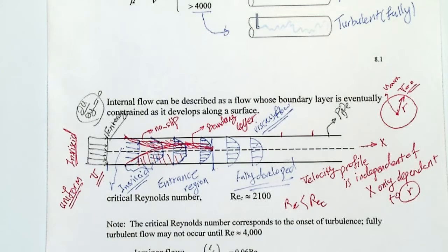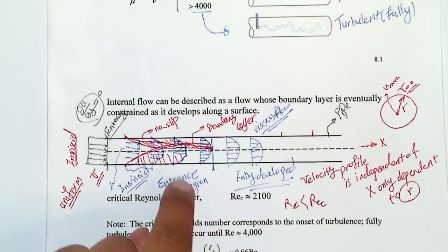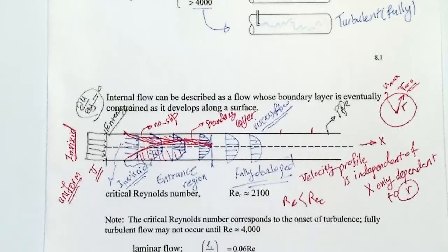So we are talking about laminar flow, which is most of the flows, especially in the human body for vessels, and also in most of the things that you have in food companies for washing. You will see that your flow is laminar because the velocity and Reynolds number are not very high. And if it's the laminar region, you have to know that after the entrance region, you will have a fully developed region where the velocity profile doesn't change.